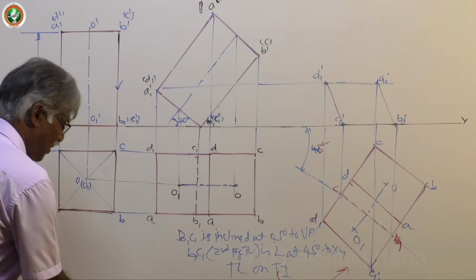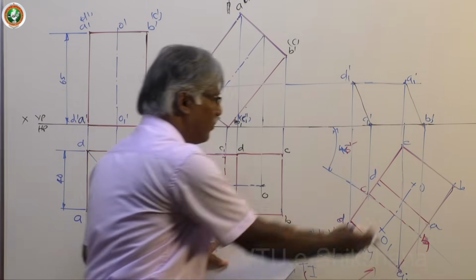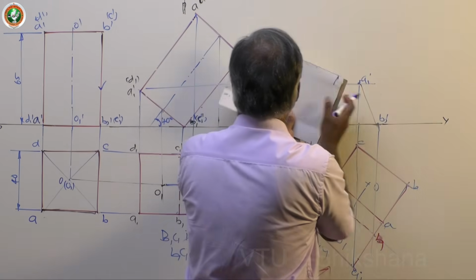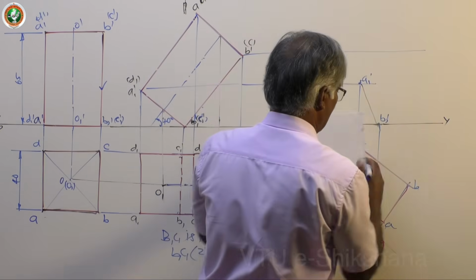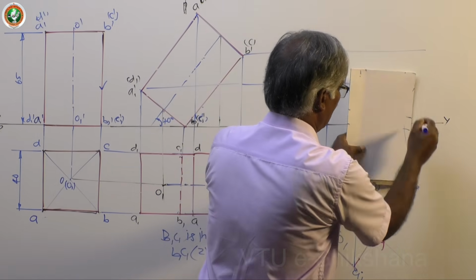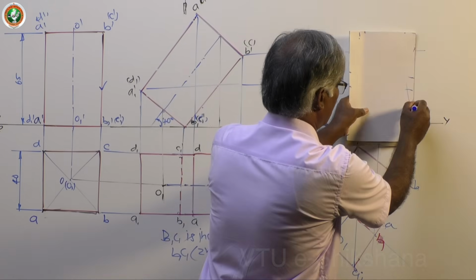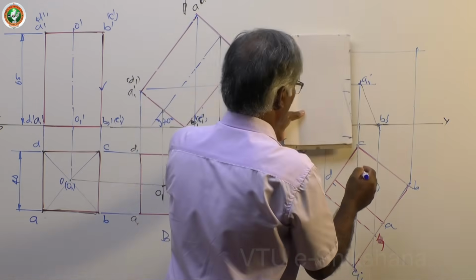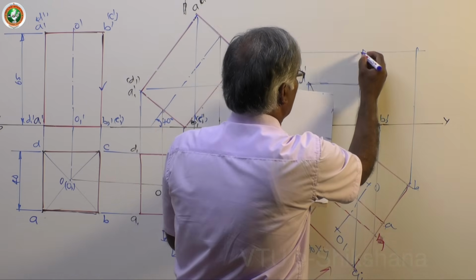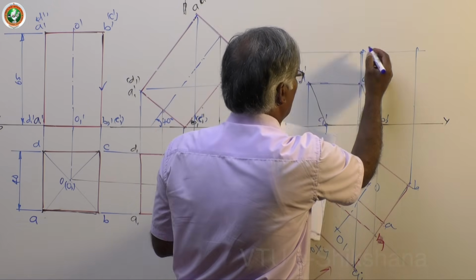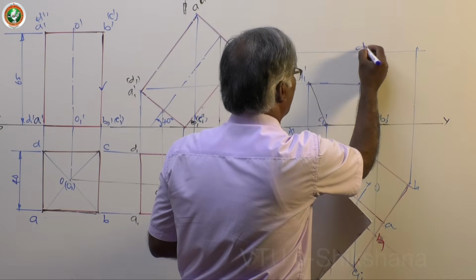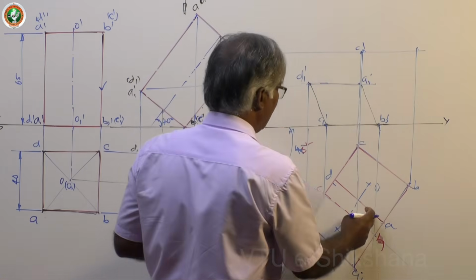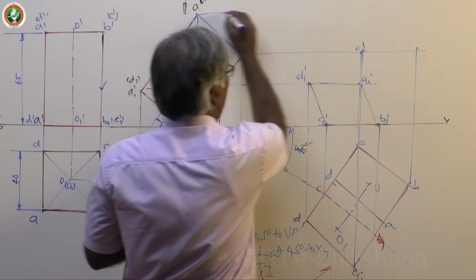So, next comes the projection from the top face. As usual, the first line refers to BC. Project one by one. Don't be in a hurry, it leads to wrong answers. This is B and this one is C. Sometimes a single line works for both, but you must be very careful. Side by side you get very close. Next comes D and A, the topmost point, right?